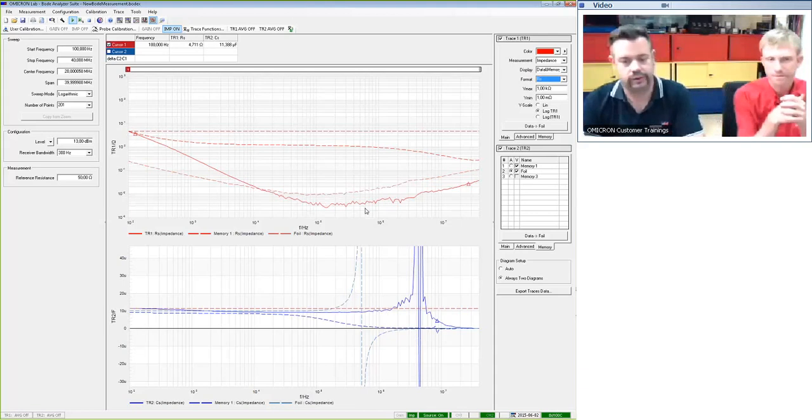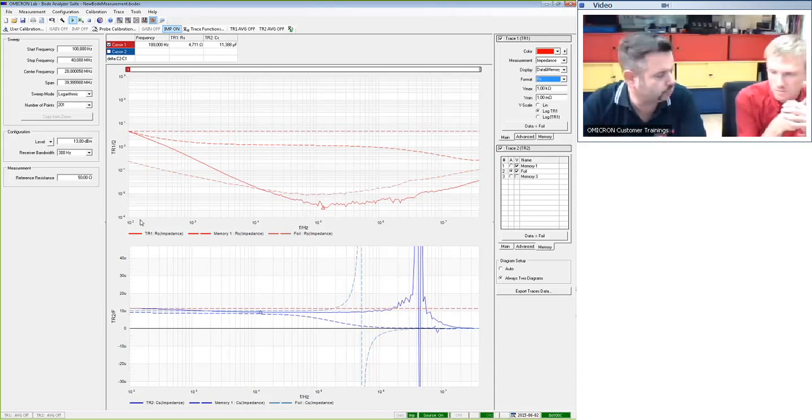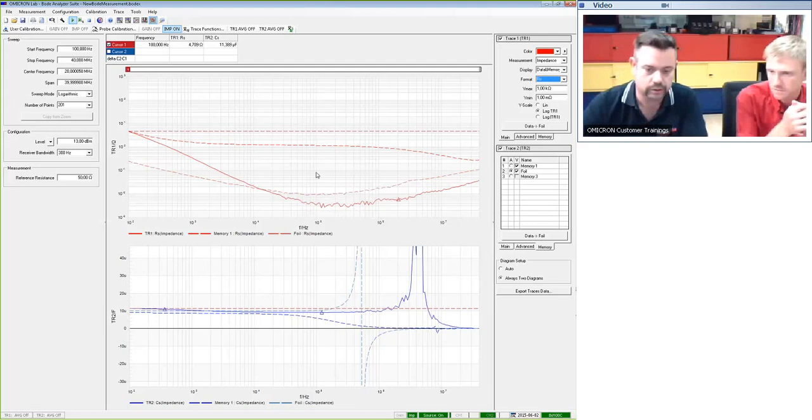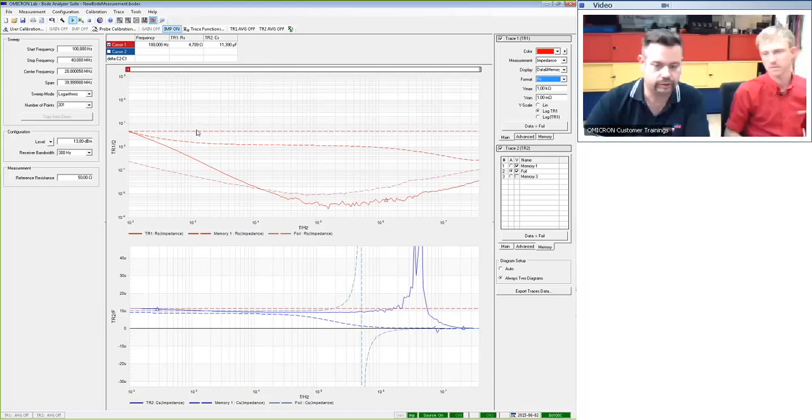And the reason for this is, as I told you, we do not recommend to use the impedance adapter for really low ESRs. So there are different methods to be used, like the shunt-through method introduced by Florian. And so you can see two different capacitors with different material result in totally different ESRs.